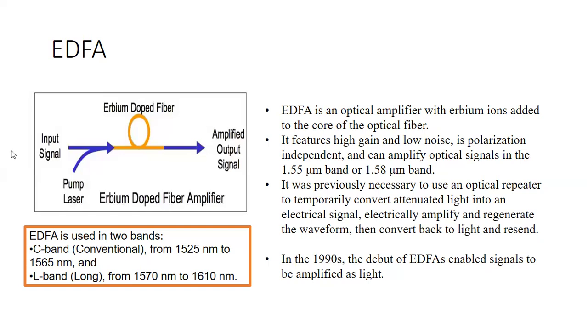So basically EDFA provides high gain and low noise, and it is polarization independent, and this can amplify the optical signals in the band of 1.55 micrometer to 1.58 micrometer, that is in C band and L band.